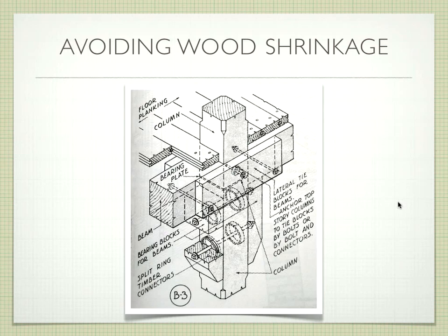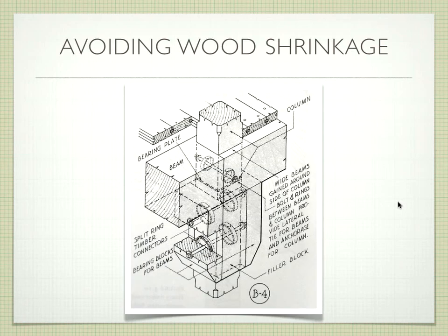You cut it into a thin little ring, you embed it half in one side of the wood, half in the other side of the wood, and it gives you a whole bunch more surface area for those two pieces not to slide past one another. Okay? Not nearly as common today, but I at least want you to be aware of what a split ring is. Very labor intensive to do, by the way.